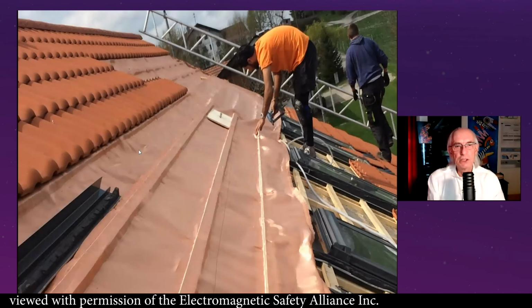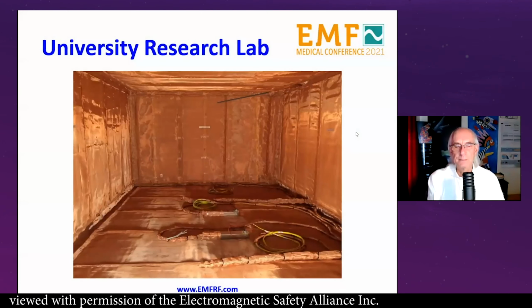You can put shielding materials on top of roofs. Very often antennas are high up, so the main surface area, how it enters the building, is through the roof. If you have a tile roof, you can take the tiles off on top, store them over here on the bottom side, put this shielding material down, attach another layer of it, and then put the tiles back on. And so you continue by moving tiles off and moving tiles back into the area.